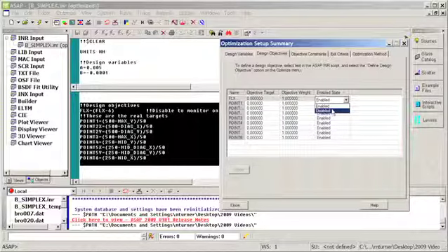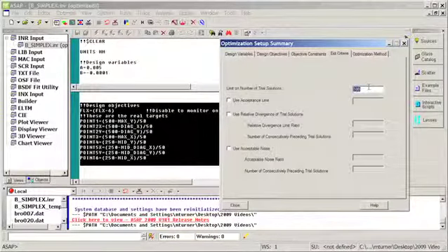And you'll notice the comment in my script file said to disable this simply so we monitor it rather than use it as part of my optimization. So I've now defined all of my variables and design objectives with simply a couple of clicks of my mouse button. What I'm going to do now is to show how the optimization state file is saved, and to do that what I'm going to do is reduce my total number of trial solutions to 10.